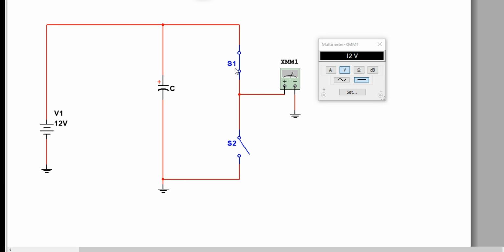First one is 0 volt and second one is voltage across the capacitor. Those voltages will be appearing across output terminals of that module. Now this is the single submodule of half bridge configuration. We can connect these modules in cascade form to get multiple levels of voltage. We will see this in the upcoming part of the video.